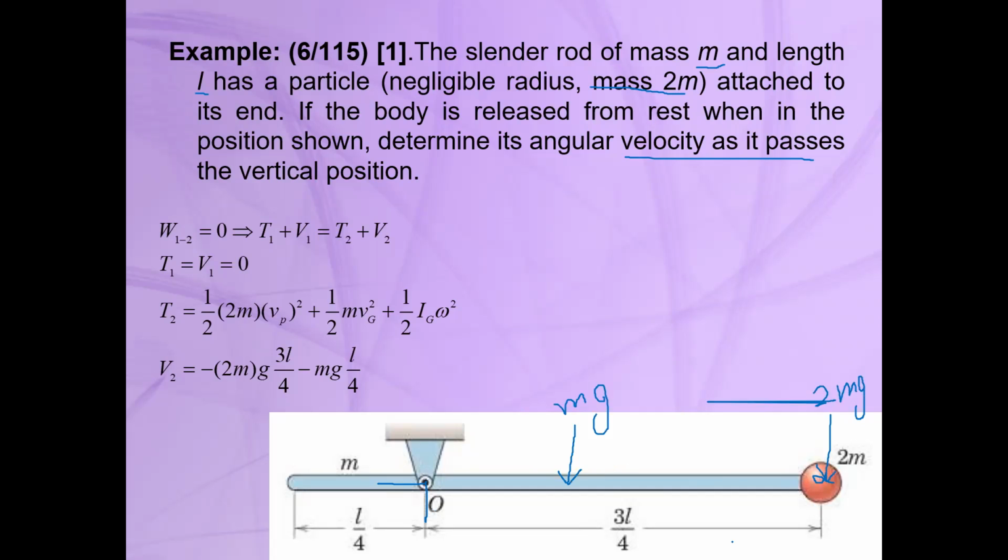And if you write the force equation and the moment equation about this point O, you can see that by rotating this rod about point O, the direction of mg will change. So it will be a function of theta. For example, if we assume that this angle is theta, you can write the equation about point O using this theta, and it will be a somewhat complicated procedure.